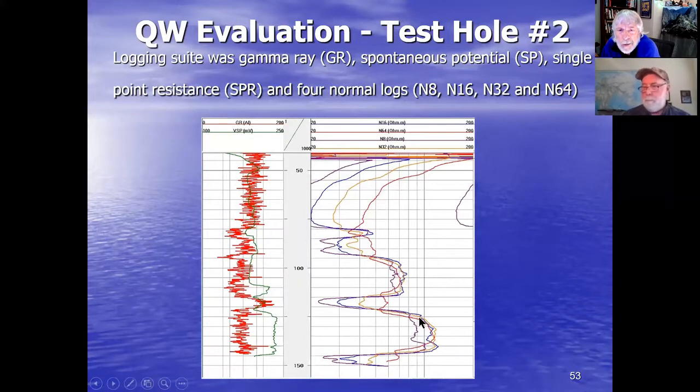What's really intriguing is this bottom horizon is so much higher in resistivity than this zone right here at about 100 feet, and then this zone up here around 75 feet. You can definitely see a different resistivity, which would imply to me a different water quality. Remember, the fresher the water, the higher the resistivity. Then you want to ask, is the resistivity tied at all to the lithology? As John was pointing out, the harder the formation, the higher the resistivity.